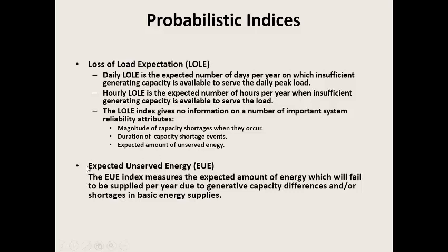The other index which has been used is the expected unserved energy. So this index measures the expected amount of energy which will fail to be supplied per year, either due to generating capacity deficiencies and or shortages in the basic energy supplies, like in the hydro, solar and wind power.